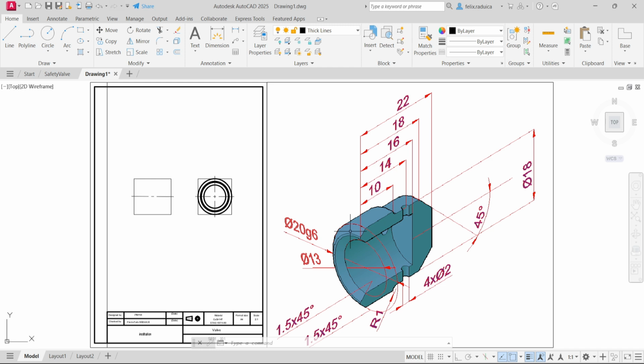So we want to start drawing the section view here. And this 10 millimeter line is with a diameter of 20. So we multiply that by 2. So we have a rectangle which can be built with the rectangle command, starting from here that goes 20 to the right. So at 20, comma 40. And this is to denote the projection of this cylinder here.